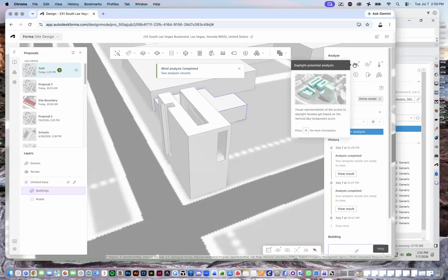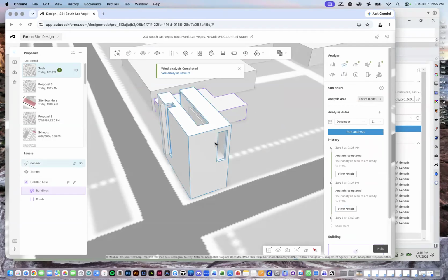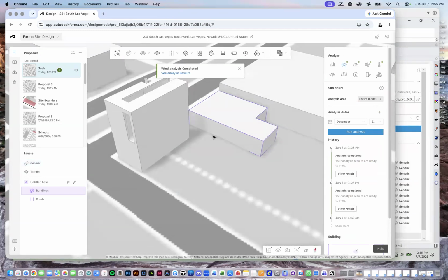All right. So that's just showing you some quick sun analysis, and I'd like for each of you to start that process. Maybe then you start to think, well, maybe I need some horizontals here on the south side if you have lots of openings, or maybe the north, maybe you need to shrink that gap if you have something on the top, or east or west, right?